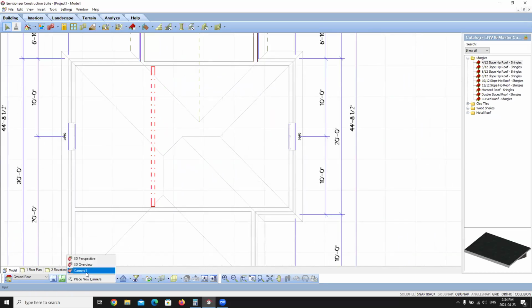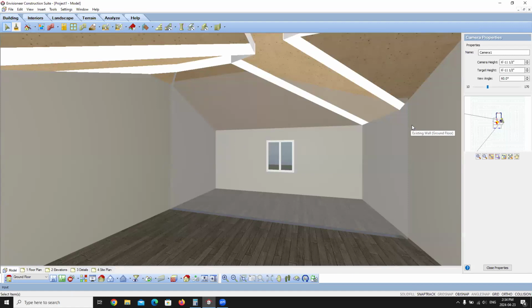And then what that will do in that 3D view is you will now see just the glass portion of that wall. So again, that is not something that you can prevent because we're making the wall glass. We're going to see through that intersection. So you're going to see through into that intersection of those two walls. So you would just step those walls back a little bit so they don't intersect.